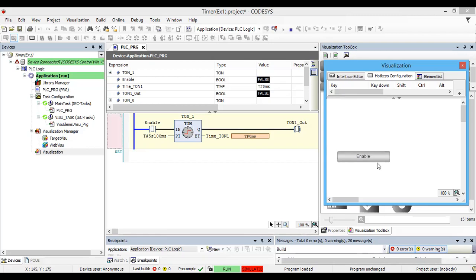Now, if you have time, I will give you 10 minutes. Open your Codesys and import this timer block and define the time as 5 seconds, add a simple contact here and make a push button. Then you can simulate and see how it works. I'll be here, and if you need any assistance, I will let you share your screen and we can figure it out, but just try by yourself. So now it's 10:40. I will give you 10 minutes to work on this example by yourself.